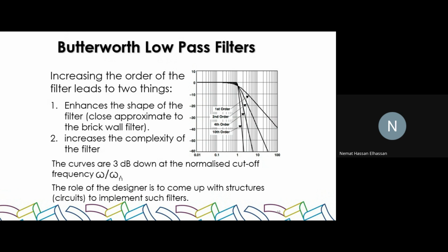If you look here at the passband, so this is passband, and this is stopband, right? And this is the cutoff frequency. In the passband, what do we notice? Zero. The gain is flat, right? 0 decibels means 1. That's normalized frequency response. So the gain is 1, the cutoff frequency is 1. Do you notice? The gain is 1 because 0 decibels means 1, and the cutoff frequency is?